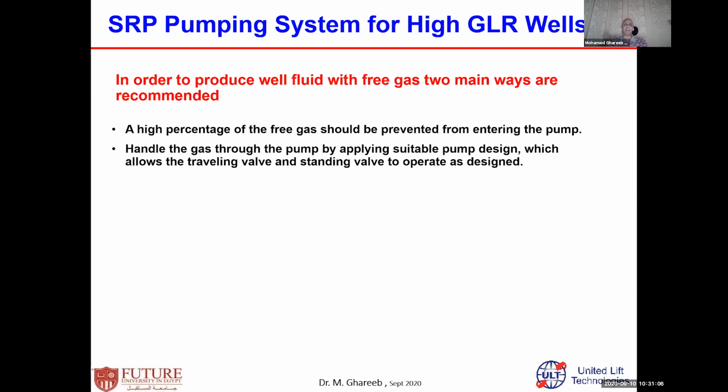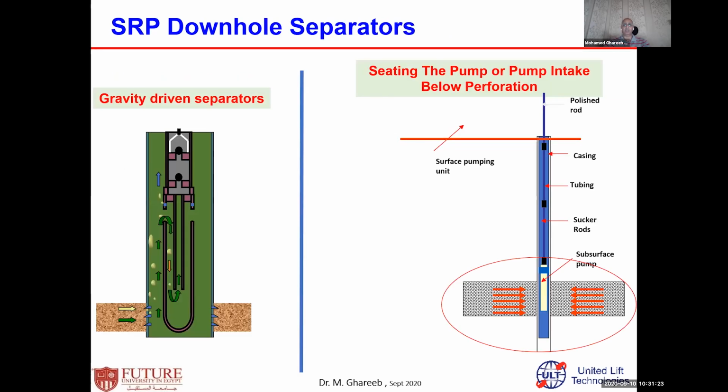Then handle the gas through the pump by applying a very good pump design. You need to run a suitable, good pump design, which allows the traveling valve and standing valve to open as per their design and so on. One of the really very good techniques and approaches usually used in the oil and gas industry for sucker rod lift systems with gas is running